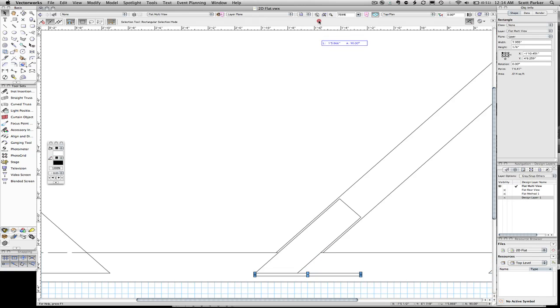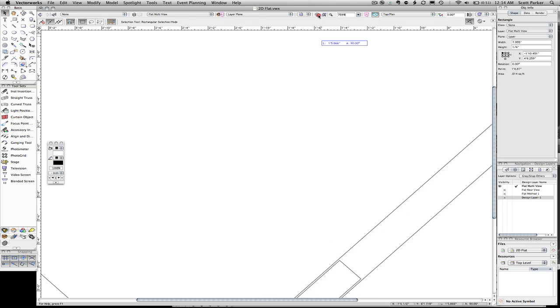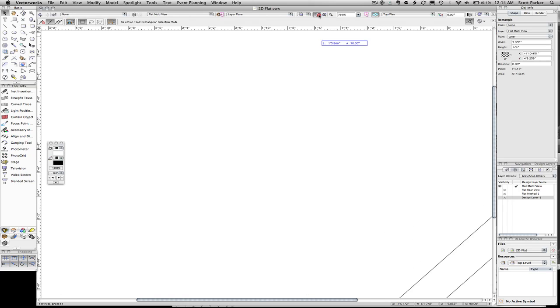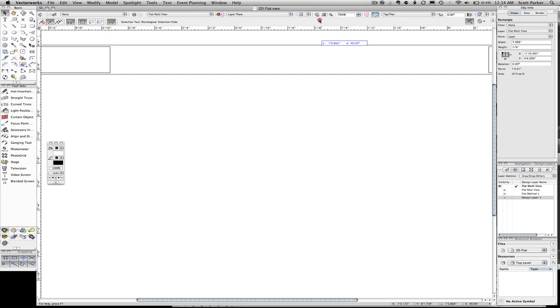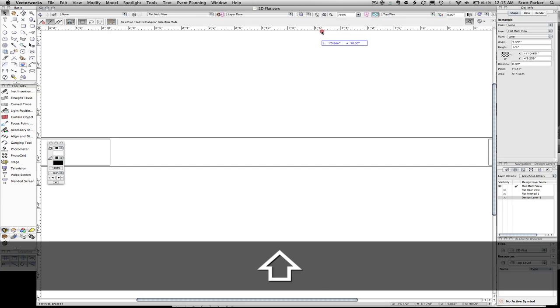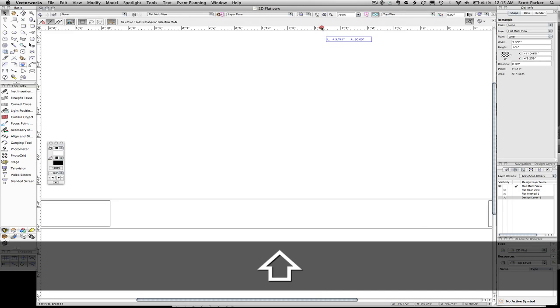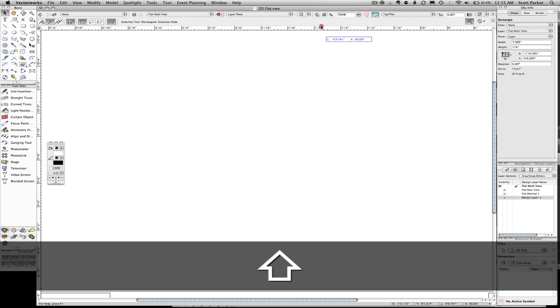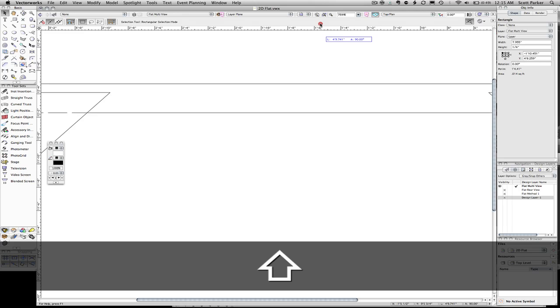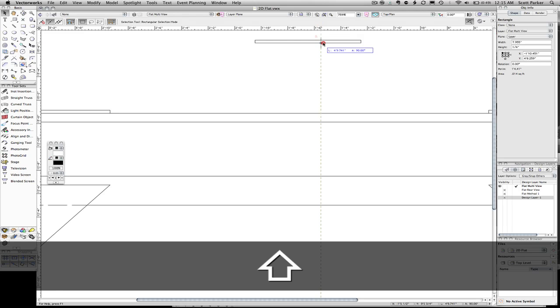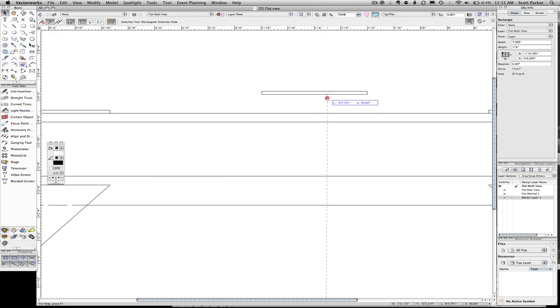Now if you want to drag something straight up or straight across, horizontally or vertically, one way to lock your dragging direction in place in one direction is to press on the Shift key. And when you press on the Shift key, it forces the program to follow the closest straight angle. In this case 90 degrees or 180 degrees, horizontal or vertical.